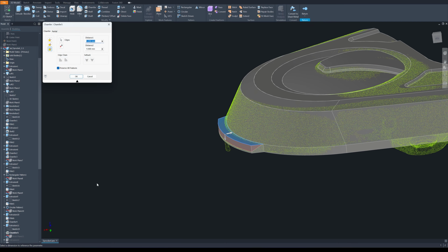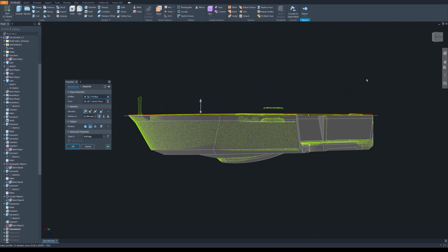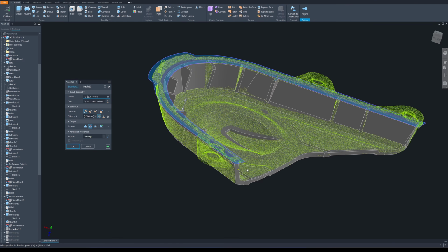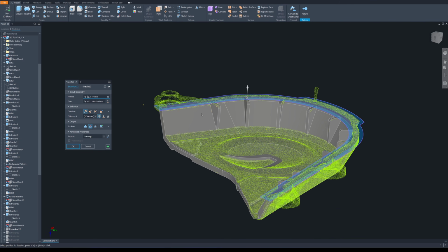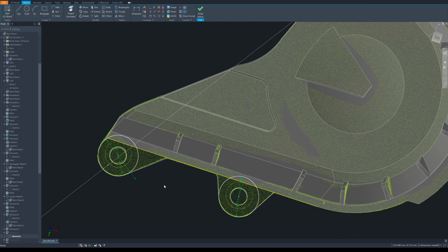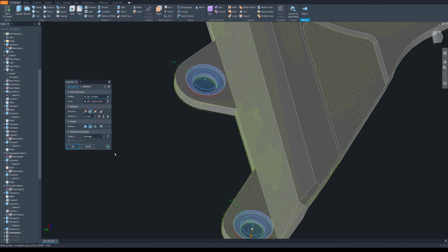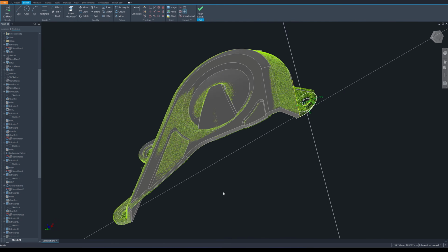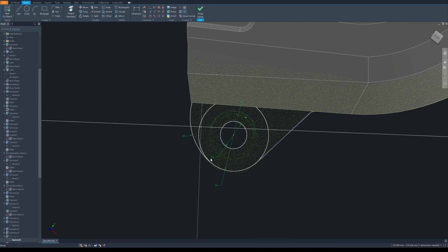I use a chamfer command to create profiles. The bottom plane here is not level, so I create a new cut using the plane to slice the sketch and cut it. Okay, next I create two sketches here for the bracket, and then I extrude it, and it has an inset for the hole. Okay, I create a sketch for the second hole, and for this one, the hole diameter is 9.5. It is smaller than the other side.